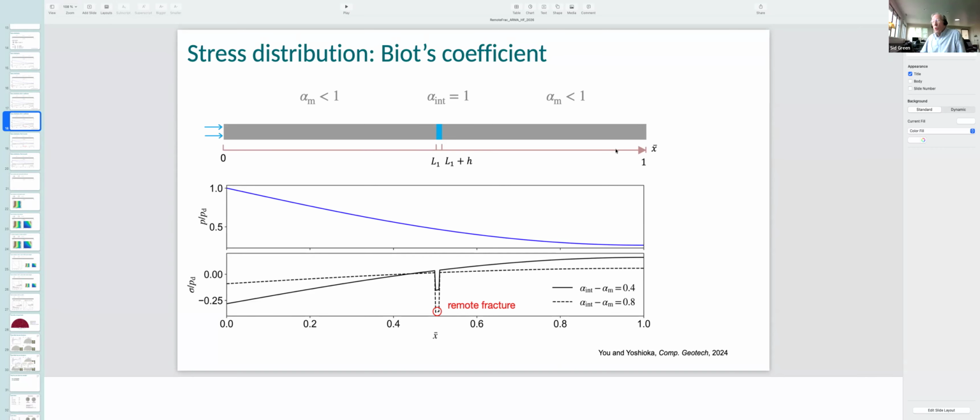I think it was a very nice job, and I compliment you on this very nice work, and going to high temperatures is very good. However, if you're building up pressure slowly, you're actually injecting into the granite, even though the granite's impermeable. You're still injecting into that granite, as opposed to if you build up pressure more rapidly, where you might tend to get simply a through-going fracture that, once it initiates at the borehole, jumps right through.